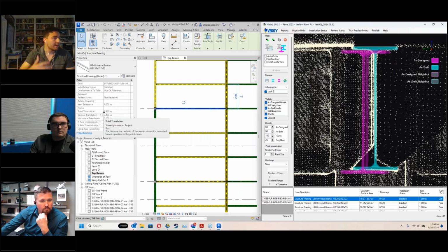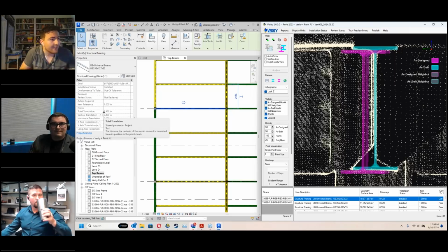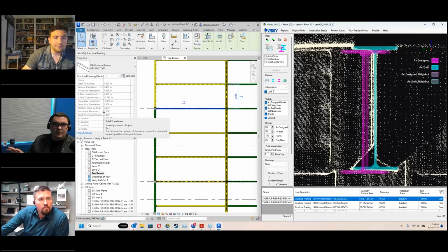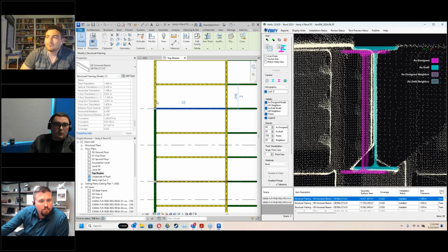And I believe, Jordan, correct me if I'm wrong, all that information then comes into where I can build schedules and use that in additional platforms, just to throw it out there, maybe like Revisto in those dashboards. And again, I think that's a... Go ahead, Jordan. No, you're okay. So everything that Verity is analyzing, all of that data that you typically see within Verity is coming in and being input in parametric parameters inside of Revit. So each of your elements has a unique parametric piece of data that Verity is bringing in from its analysis relative to where the scan data is in comparison to your actual element. So all of this can be scheduled out. You can run reports on this. You can create tolerance schedules.